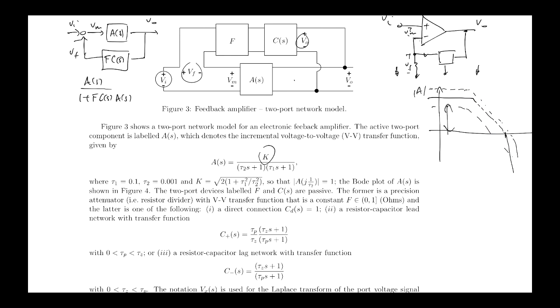All right. So the closed loop system, in the style that we've been representing them as block diagrams, will look like this, all right? You can see by Kirchhoff's voltage law around this loop here that the voltage across the terminals of the op-amp is just the difference between the voltage applied at the input to the positive terminal, right, and what's fed back, right?